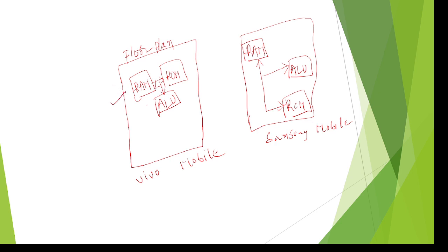So finally, a good floor plan or good placement will reduce the power consumption as well as increase the speed. Otherwise, noise will increase and more heat will be generated because it consumes more power. After placement, there is the routing process. Good placement and good routing always reduce the power consumption, increase the speed, and reduce the chip size.